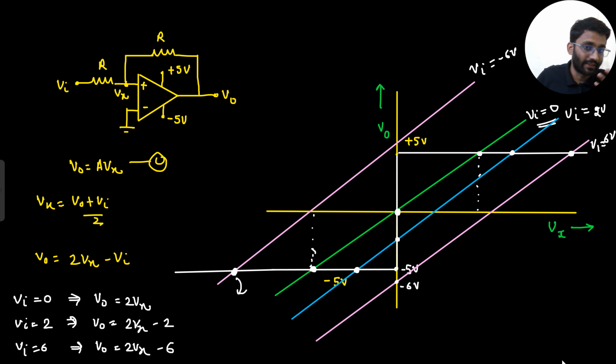And then you can also tell that, sir, here virtual short will never be valid because here the Vx values we are getting are always different, not equal to 0. Here Vx is different. Here Vx is somewhat here. So the Vx value is always different. Vx value is not 0. So that's why virtual short is also not valid. Got this point? Understood this analysis? And I hope you liked the analysis as well.